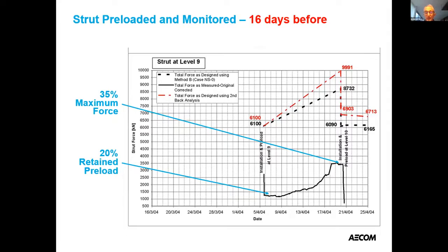Now, nobody noticed this. If you're applying pre-stress, you normally apply it with a jack just a few percentage more than the design preload. So when you lock off and the wedges draw in, there's perhaps 5% loss. And this is carefully monitored, say in post-tensioned bridge decks and so on. And people make sure and study these things very carefully.